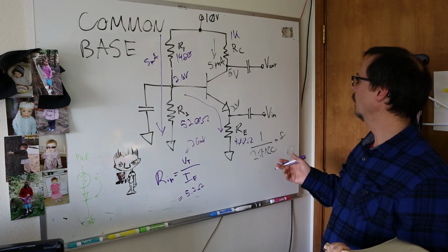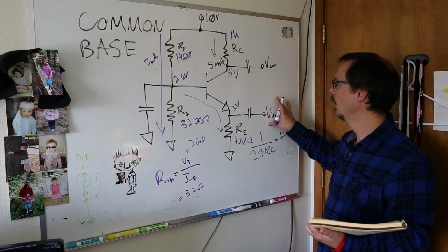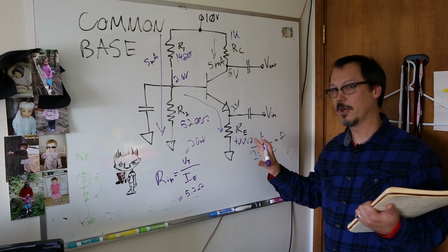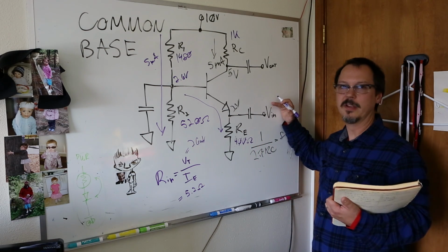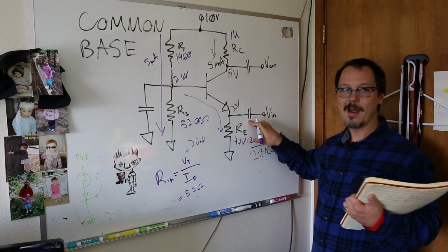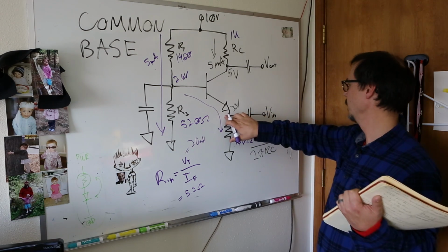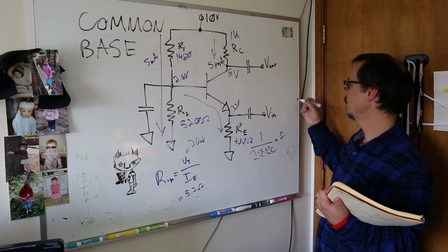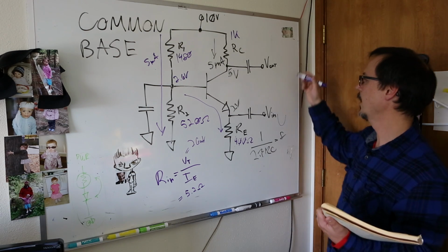Let's talk about how we expect it to work, right? So if you've got an input here, and I always encourage a mechanical understanding of what you're actually looking at. So you're putting in a signal at V in, right? There's an instantaneous voltage that occurs at this point, because for that cap, the signal sees a short, right? So you can expect your signal is going to appear there, and that's not even going to be in the circuit.